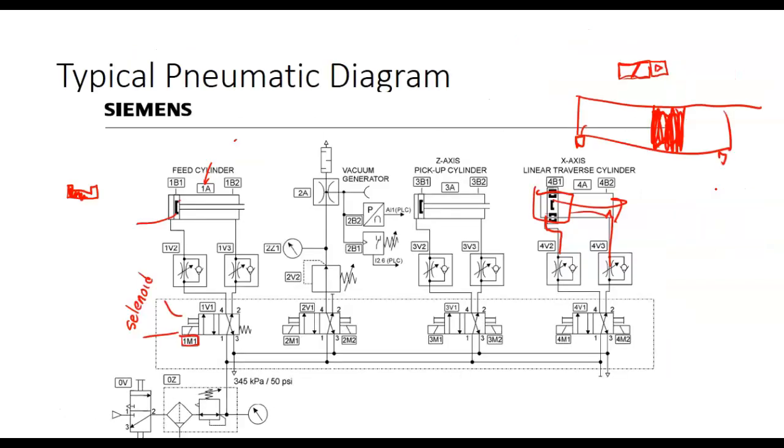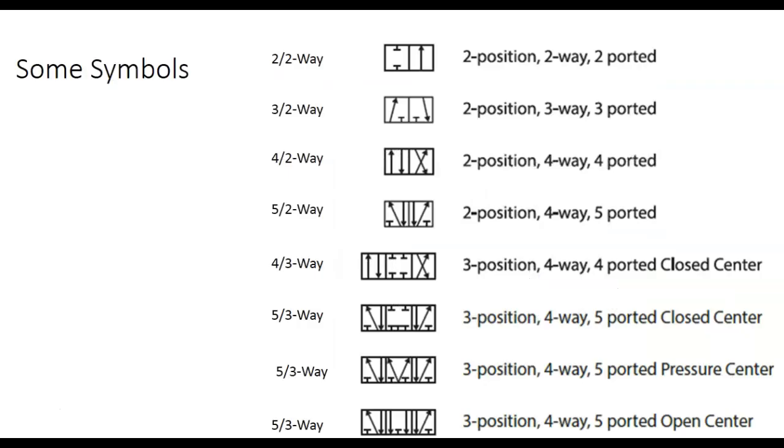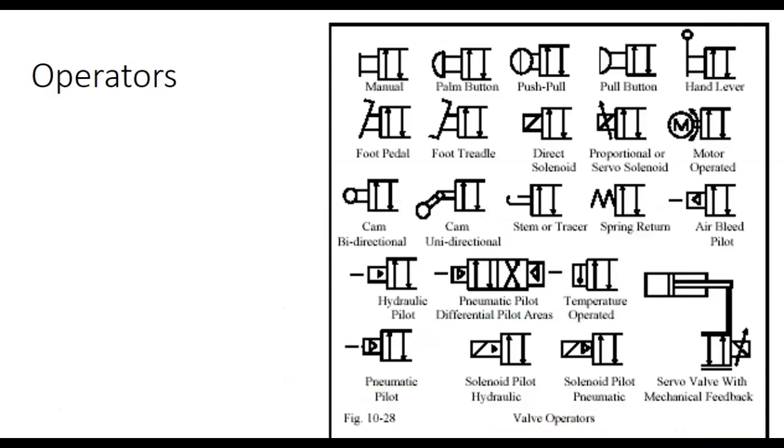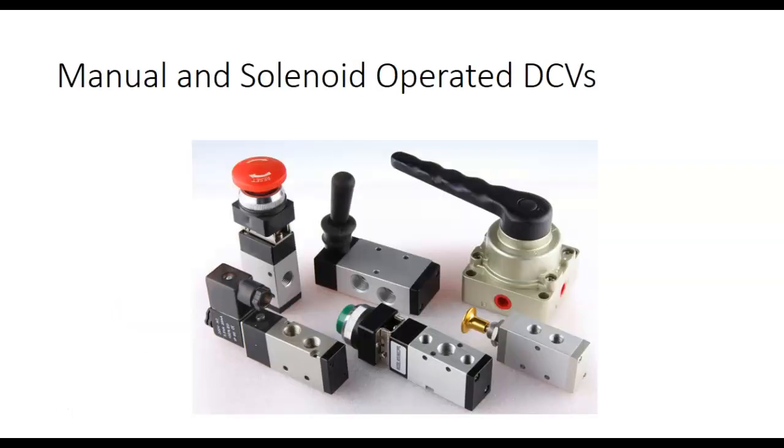They're using two of them to get this valve right here. So when they're turned off, it puts pressure on both sides of the cylinder. Each one of them is pushing against the other, and they don't want to move. Right? Understand? They could have done it with one valve with a pressure center, but they did it with two valves, doing exactly the same thing that valve right there would do. And they're using the same feature, by the way, on the Festo line.